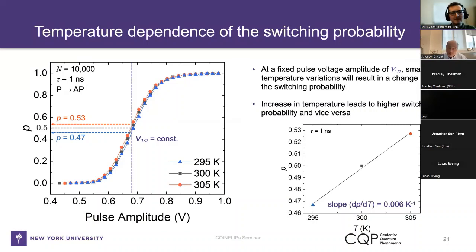For example, for the superparamagnetic devices, the devices that fluctuate simply by reducing the barrier, the switching rate is exponentially sensitive to temperature. So if you're going to build a device, you want to know how sensitive it is. How accurately do you need to maintain the temperature, or do you need to do something to adjust it? How much overhead do you need? The less sensitive it is, the better, but you would expect sensitivity.